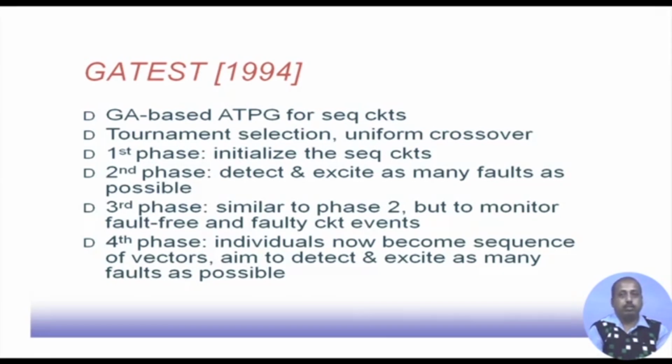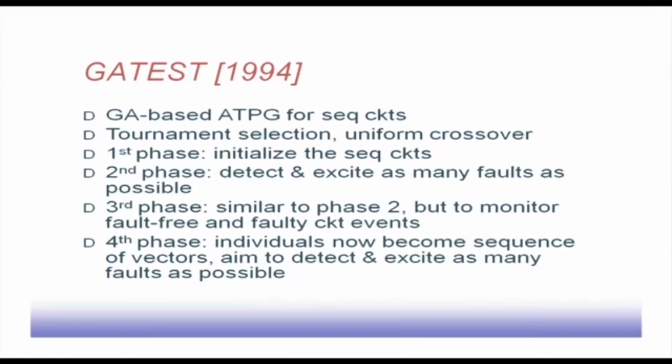You see that this is a sequential circuit. First is the sequential circuit initialization, which is a big challenge. The set of patterns that can initialize the sequential elements to some distinct values is important. That is the fitness function for the first stage. In the second phase, the objective is to detect and excite as many faults as possible. This is similar to the previous test pattern generation we have talked about.